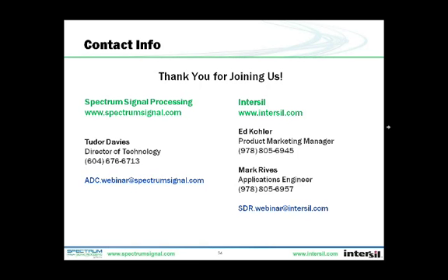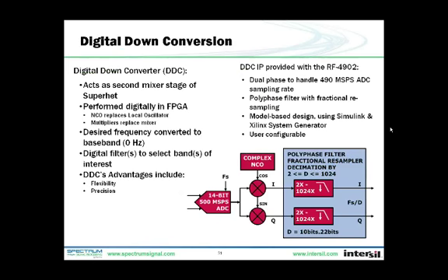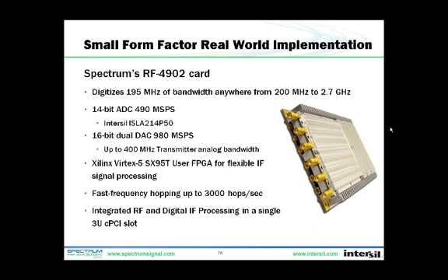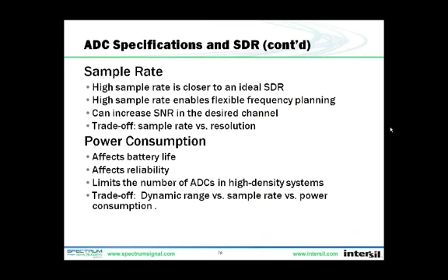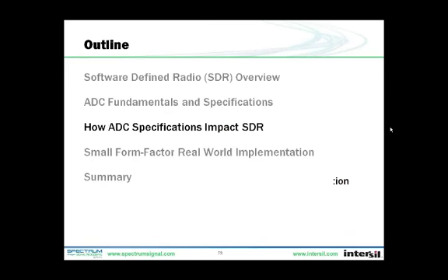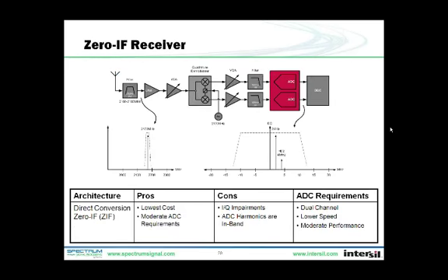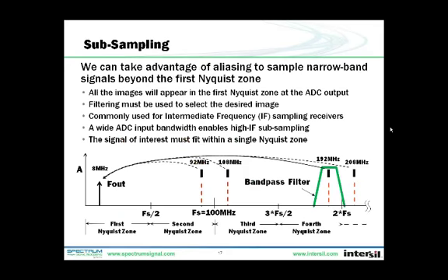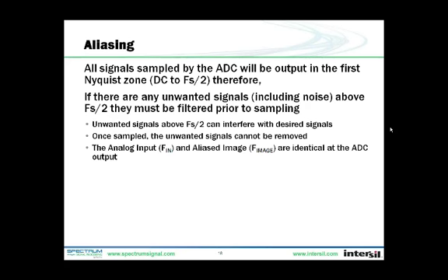Okay, the next question we've received. Earlier in your presentation, you described how one parameter, possibly SNR related, is improved by removing one part. Can you review this again? I think I mentioned that the jitter degradation of SNR can be improved if you use a lower jitter clock. Is that the reference?